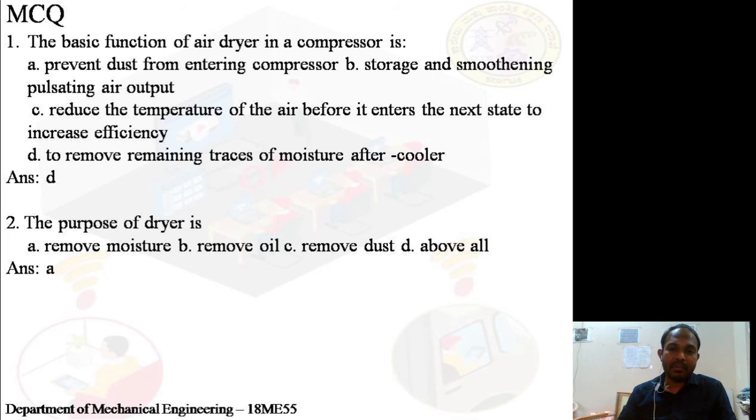So for the lubrication purpose we may use a small amount of lubricants in oil state. So these oil traces may mix with the water content and form tough, rigid structures, which we call gel-like structures. They not only restrict the movement of the air but also restrict the movement of the mechanical parts. So that is the biggest problem with this moisture content. Is it clear? That is the reason why we always remove the moisture content in the air by the use of air dryers.